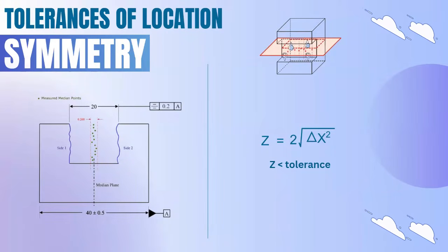These three are the same. So in the 2018 update, ASME has removed concentricity and symmetry. We can check symmetry and concentricity in position itself.